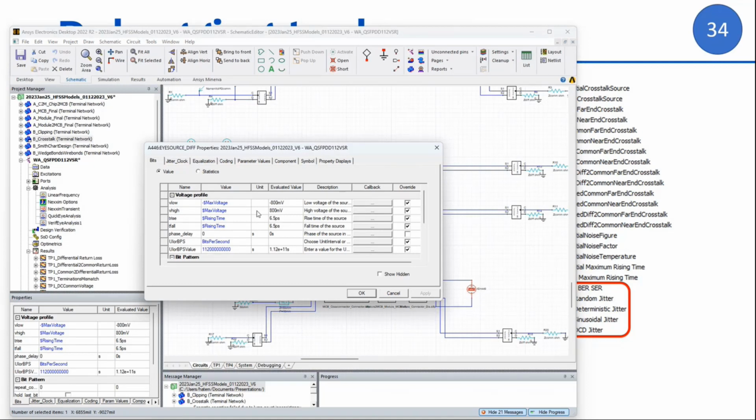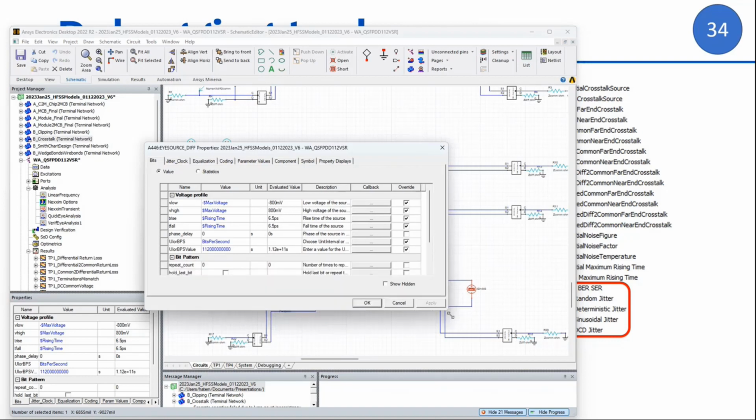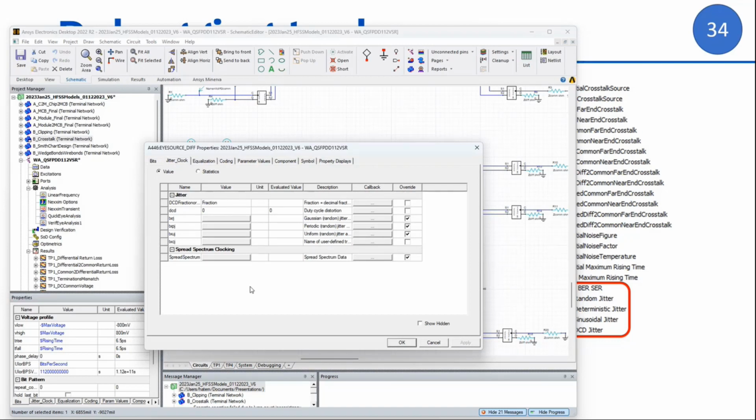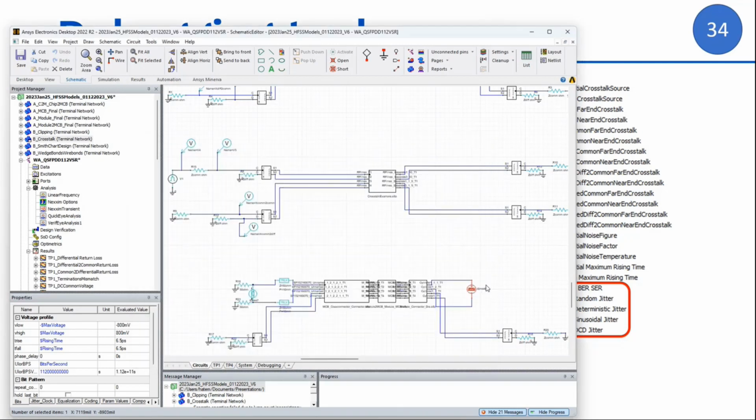the transceiver. So here I can specify the maximum voltage, the minimum voltage. I can specify so many things. I can also add jitter. We have all kinds of jitter: DCD, random, pseudo noise, name it. The reason why you would do that is you want to see if the chip inside the transceiver has some sort of defects or limitations and is adding additional jitter to the nice clean eye. What do I expect to see here? So this is something you can use.